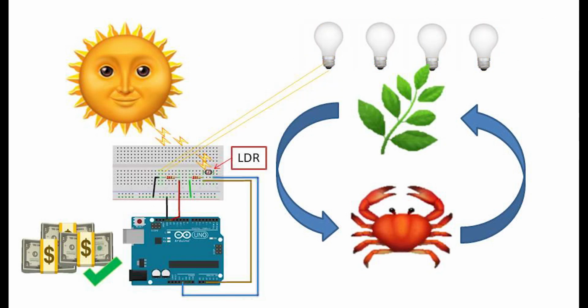Therefore, consider example 6 of our previous Arduino project examples. It is a setup with a photocell. When the photocell does not detect light, the resistance is high. This will be detected by the Arduino board through the analog pin, and it will turn on the LED.